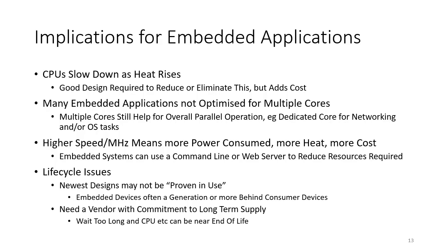Now, in some cases, using a single core, you can get very high performance from that single core, but in other cases, you might find you're quite constrained because the chip just isn't designed to run multiple cores at the same time. So you do need to take care of that, and that might require that your embedded application does need some optimization. Ideally, the more cores you use, the more your load is spread across those multiple cores, the faster it will run overall, and without having to increase the temperature too much.